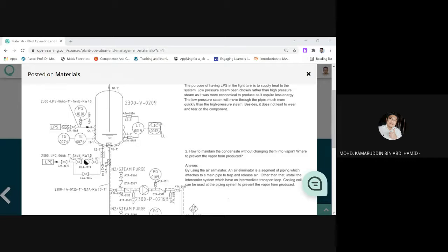And when this liquid has accumulated, when the liquid in that round self-operating, self-regulating release valve is full, you need to release it or change it. In order to do that, you need to do some bypass. As usual, you close the two valves, front and back, then you bypass, and you can do maintenance or whatever, and you may reduce the liquid over there.